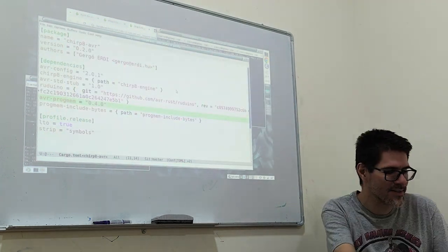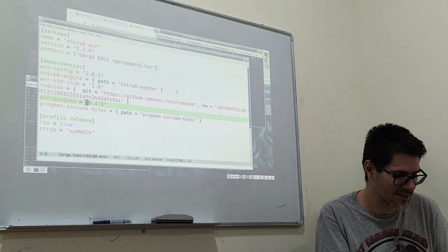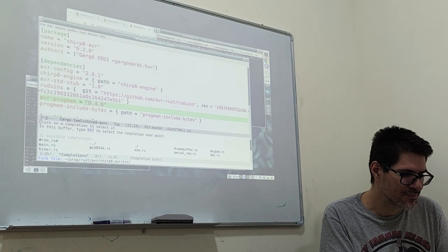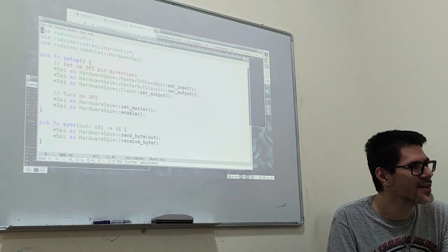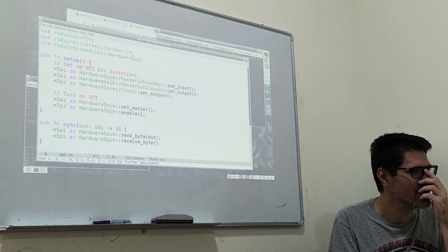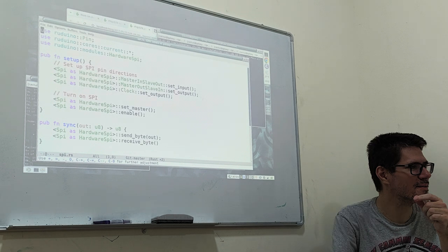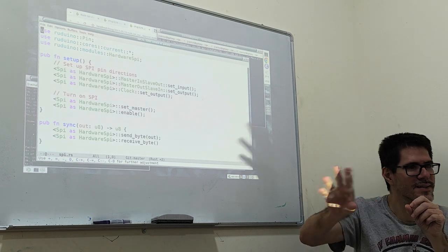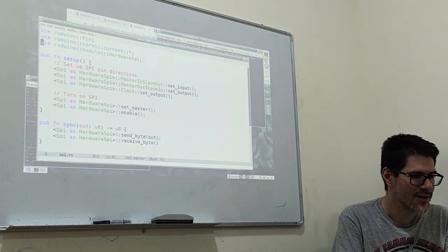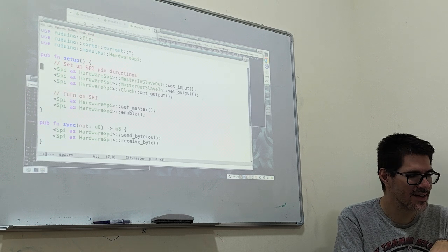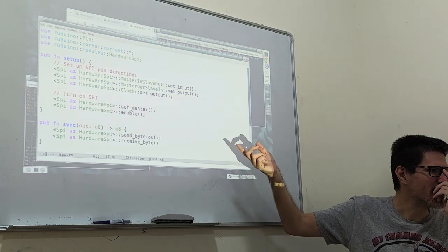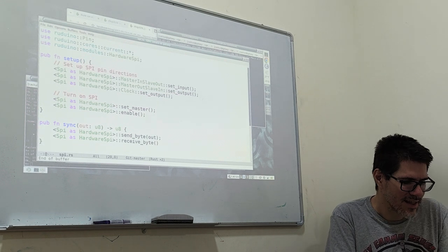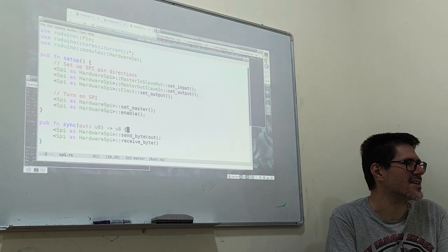And so, okay, now just to answer your question about what it actually looks like on the inside to interface with the peripherals. The AVR chip itself has an SPI interface, so you don't have to bit-bang, you don't have to implement what it means to send something out by SPI. There's a special register, you set it to an 8-bit value, and it will shift it out. And like I said, there's this Arduino library which has a very nice interface to doing that. You see that this is super readable compared to writing magic values to magic memory addresses. And if you want to send something out, you just send it out, basically.